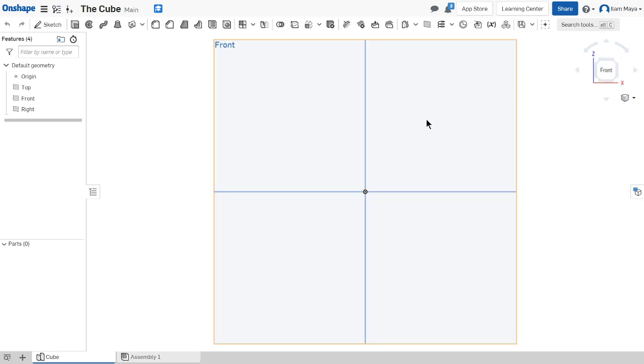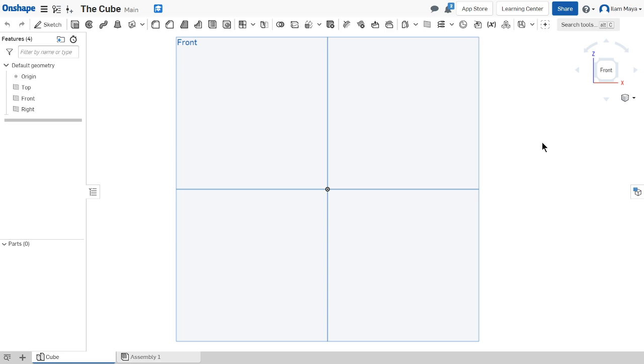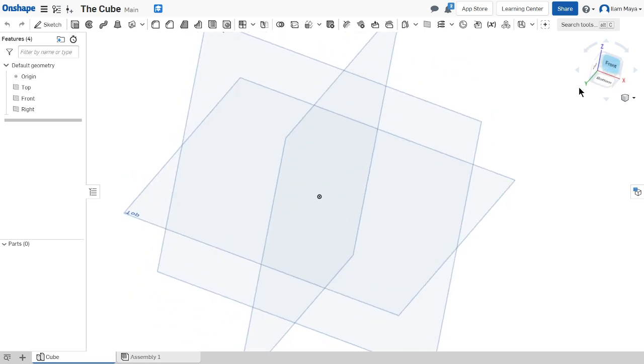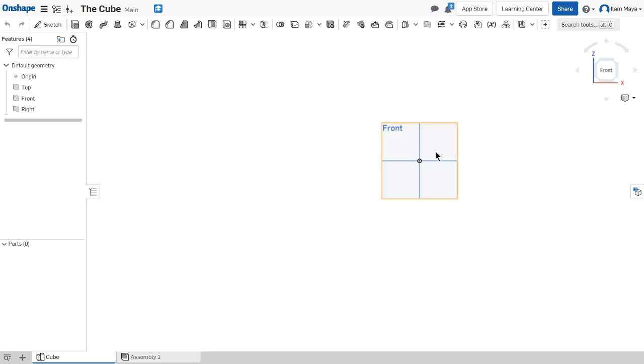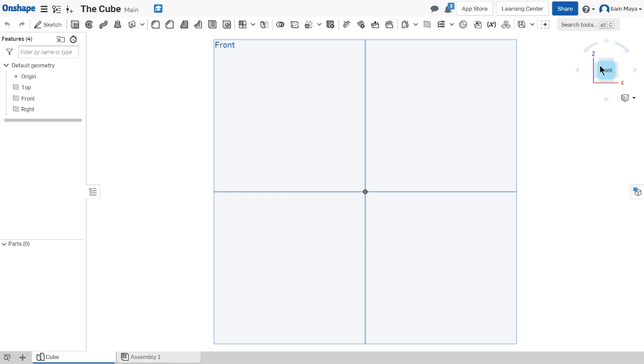Also, for the controls, I would recommend using a mouse. Middle click, I'm clicking middle click right now, is used to move this. Right click is used to rotate your view like this. So those are the general ones you need to know. Oh yeah, and zooming in and out is done with your scroll wheel. You can also use your trackpad if you have a laptop, but it's going to be much harder to use. So just make your life easier and use a mouse. So anyways, let's get to the point.